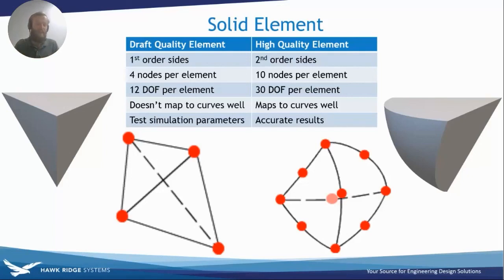There is a weld connector inside of SolidWorks Simulation, which will allow you to simulate things like radial welds. But if you're using a graphical weld inside of your drawing or inside of your weldments feature, then if it's not actually solid geometry, it's not going to translate into the simulation environment.